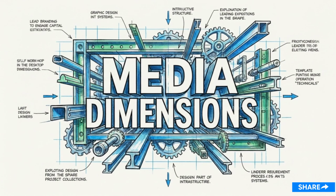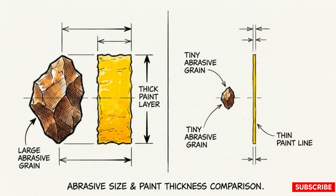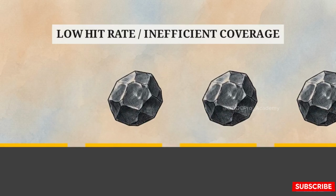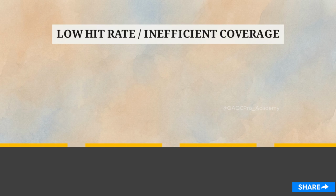Factor 1 is particle size. The general rule of physics here is straightforward. Your largest abrasive particle should equal the exact thickness of the coating you are trying to remove. An oversized particle stripping a thin coating creates a low hit rate, dragging down blasting speed.